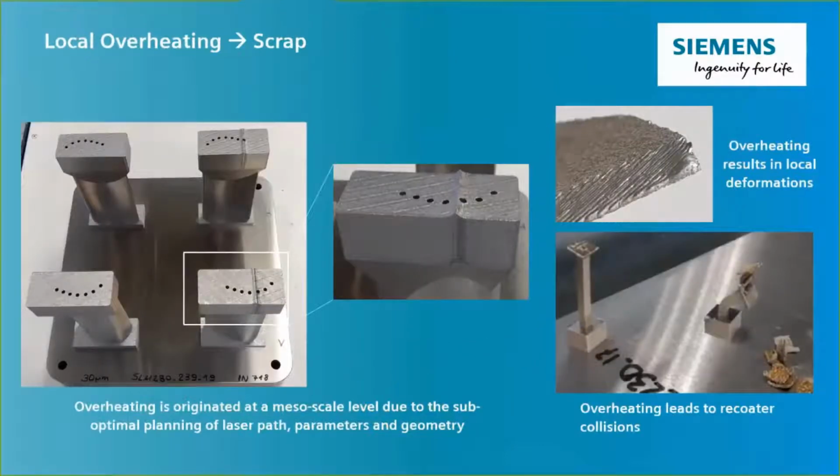So by my definition, hyperlocal overheating, it's a real issue for AM because it can be the root cause of some of the problems we talked about earlier. So a distortion might occur because of these things, as we see in the images here on the left. But again, it can also cause things like small deformations and overheating that causes large deformations, leading to things like recoater collisions.